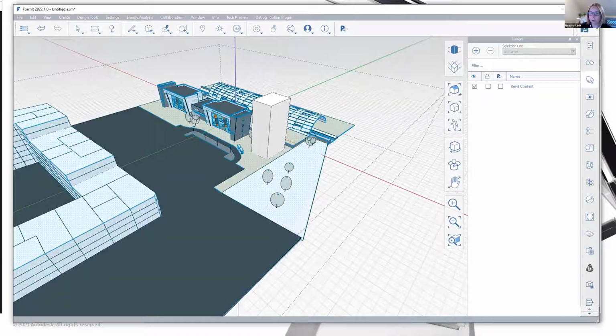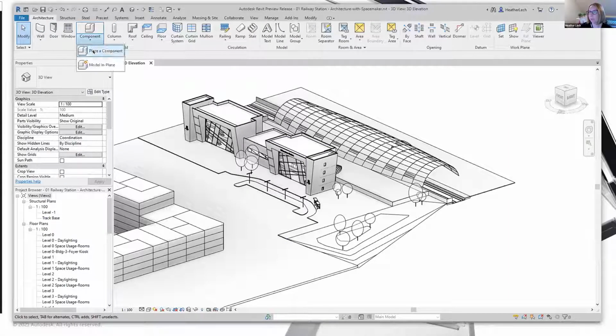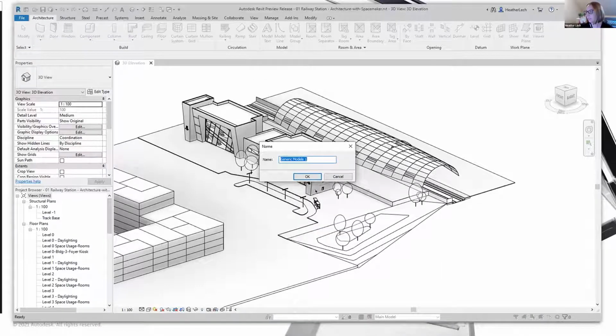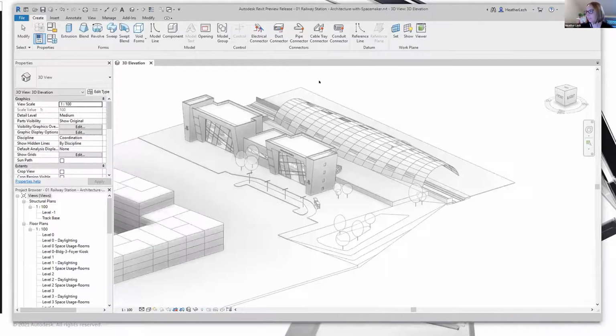in Revit, before I click the Send to Revit button, I go back into Revit. I could go into an in-place mass, and pick a family type like generic model or massing. So I could go in here and say generic model. So now I'm in the in-place mass mode here.